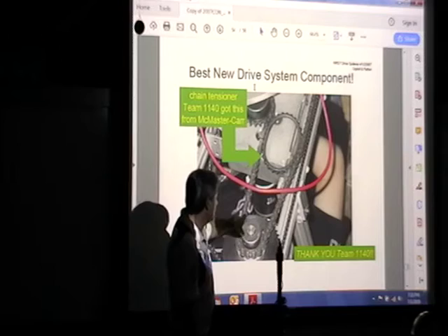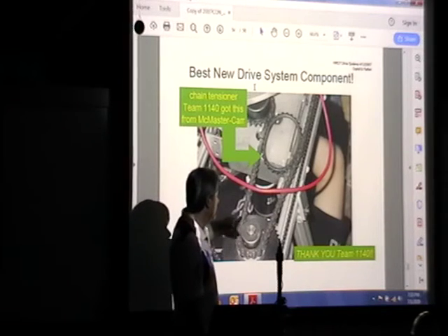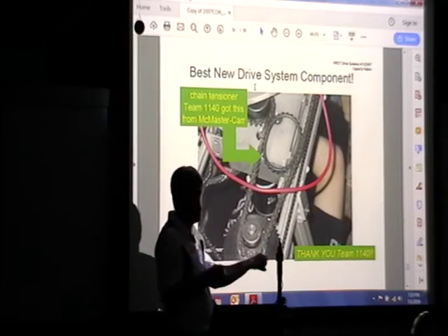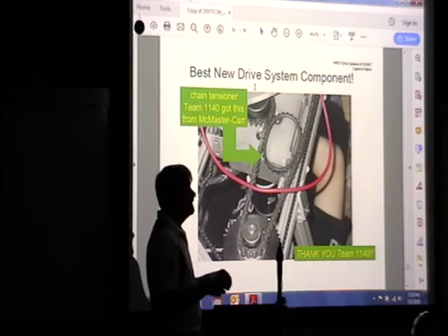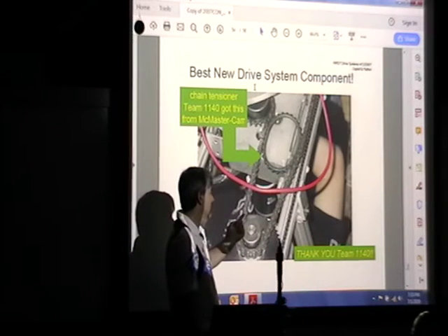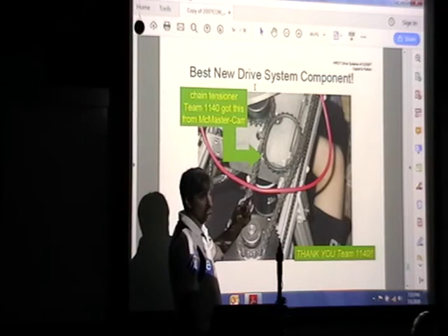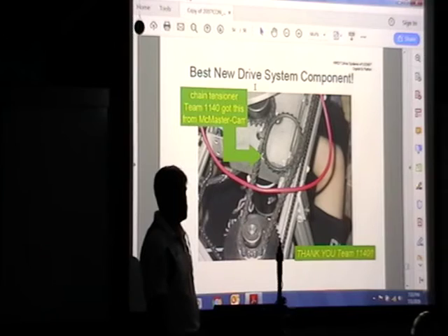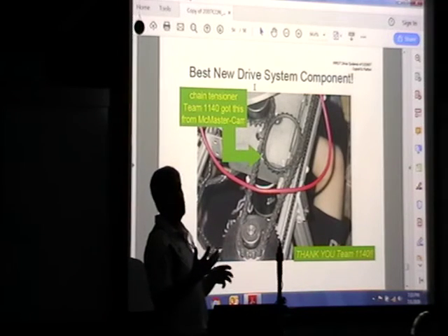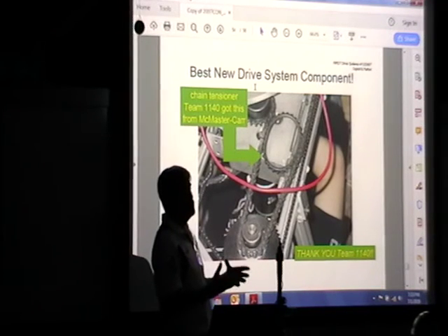But these chain drive segments not only have a static load when you tension the chain, but also when you're kicking that drive system in, that generates a torque, which generates a force, which in turn generates a radial load on that shaft. So that's where you have to consider not only the static loading, but the dynamic loading of your system.